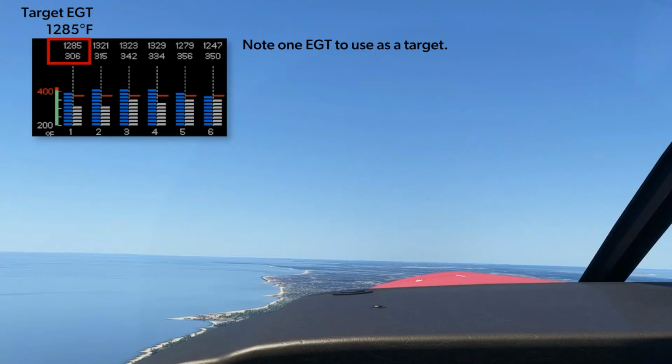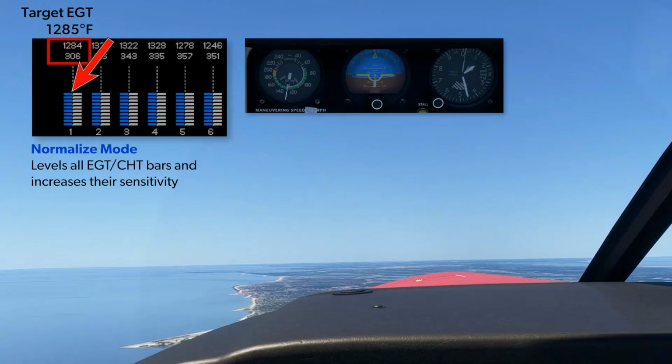And then as you climb, actually, I'd also suggest normalizing the engine monitor. Normalize mode on your engine monitor, if you have it, levels all the EGT and CHT bars at their current values and also increases their sensitivity. And we're going to be looking for deviations from where they are when you normalize it, so that makes it all the more easier to do.